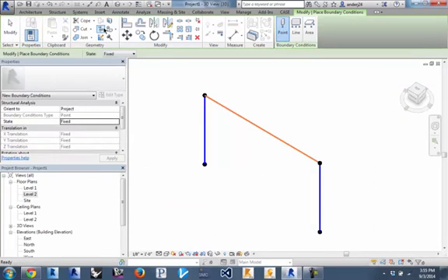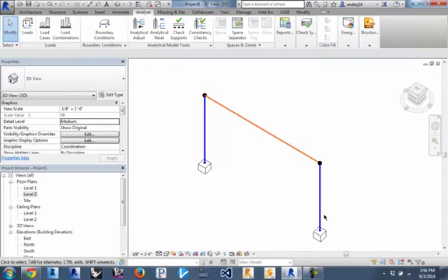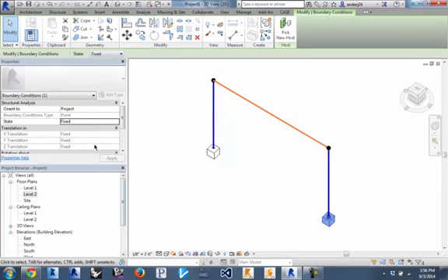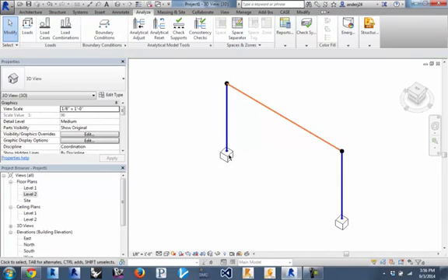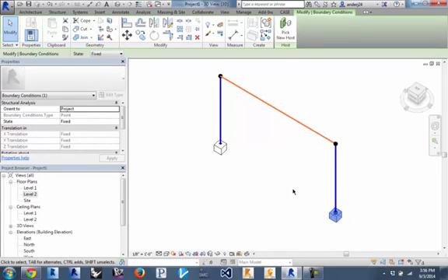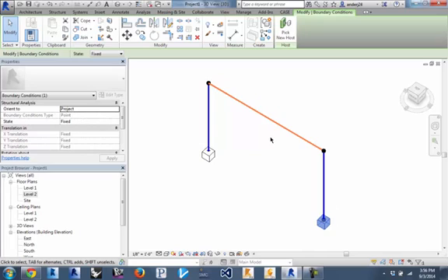So once that's done, you should be able to apply your boundary conditions. And these are the conditions for the column in this case. So in this case, I see I applied a fixed state. I can update any of these for however they are. So when you're dealing with beams, cantilevers, things like that, you can assign these different boundary condition states. Question? All right. So for now, we're just going to do 2 columns, a beam, 2 boundary conditions, and then we'll just apply a dead load to this, and then we'll start taking this into Robot.